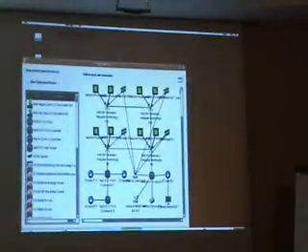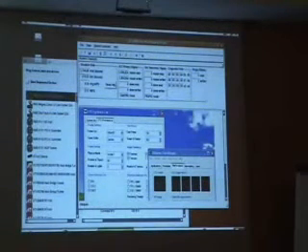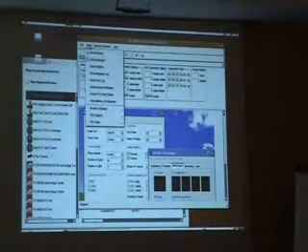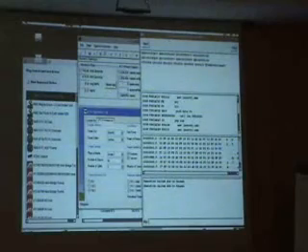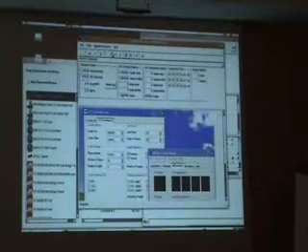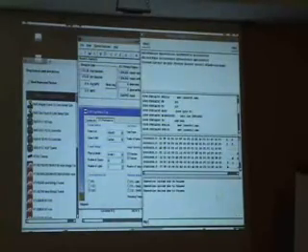And for debugging the guest, there's a couple of ways you can do that. Basically, there's a debugger in SimNow, which allows you to turn it on. You go in here and view, just like you can view the devices, you can view the debugger and the registers. If we view the debugger, as you can see, it's halted. But if you say go and then stop, SimNow will update the processor, and here's what the memories look like.